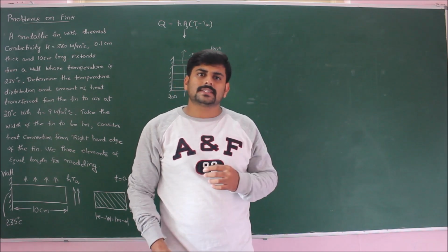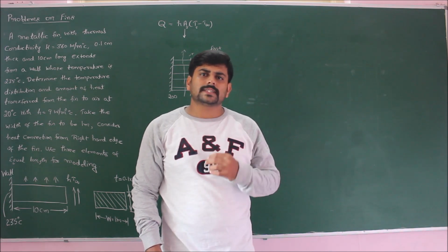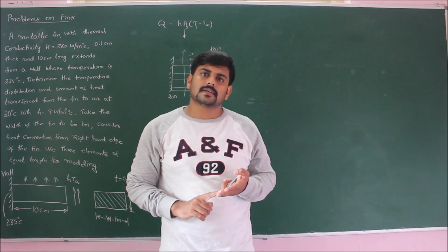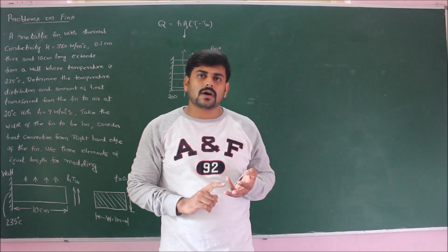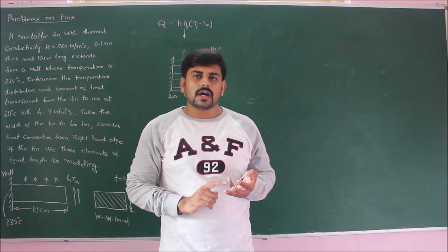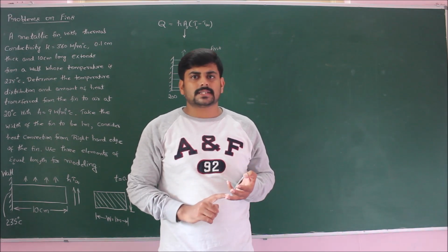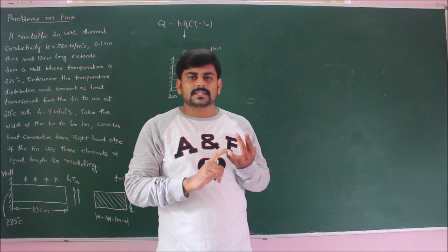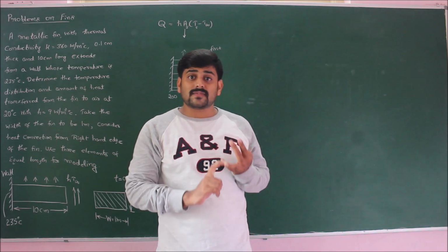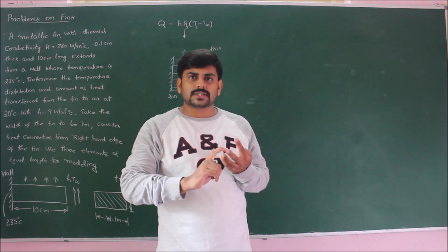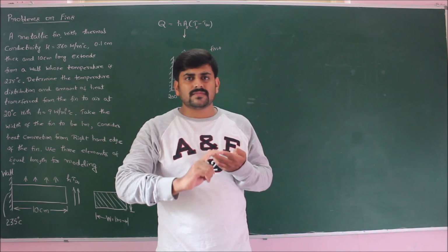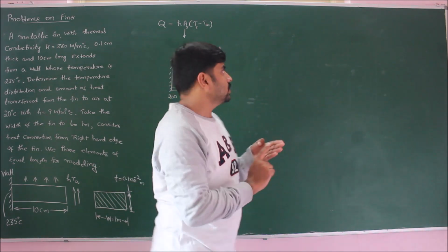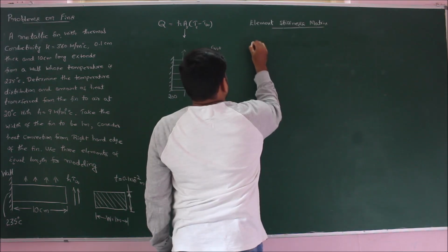Now, in lecture 2 of module 4, we derived expressions for element stiffness matrix and load vectors. In case of fins, the modes of heat transfer to be considered are conduction and surface convection for all the elements, whereas the end convection depends on the boundary condition given. So for the element stiffness matrix, one should know the element stiffness matrix due to conduction, due to surface convection, due to left end convection, and due to right end convection.